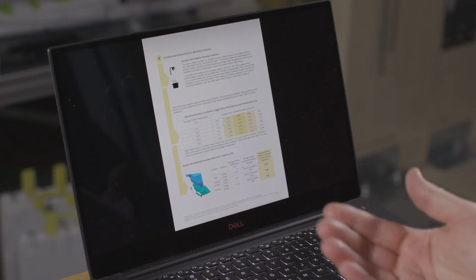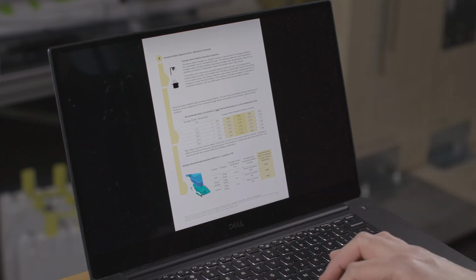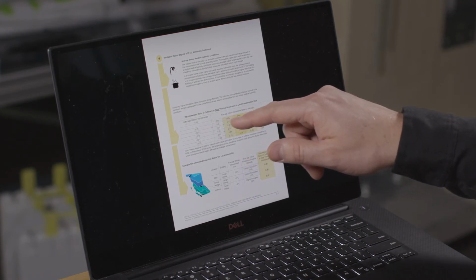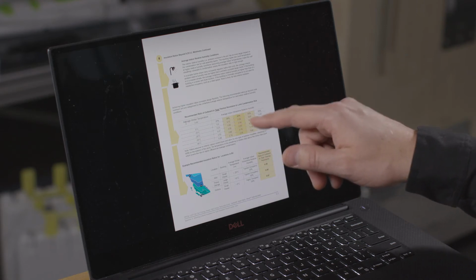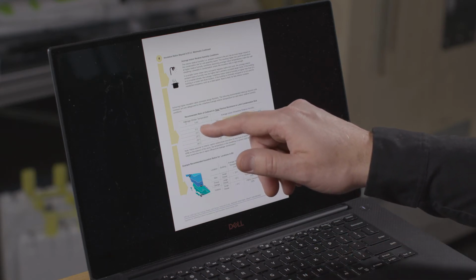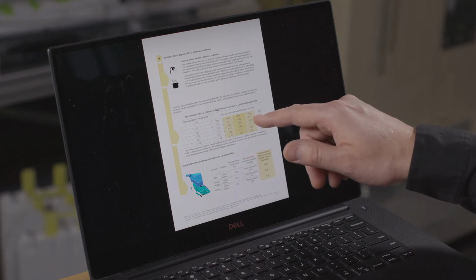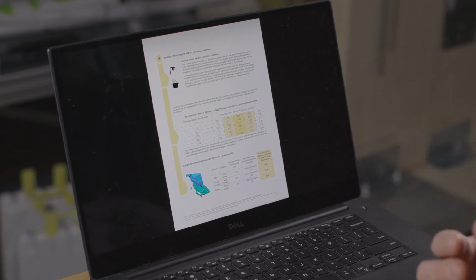When you follow through the building science discussion there, it then gets into some guidance. Okay, what ratio should I have, or what ratio would be safe for this wall assembly? If we look here, we have this table of ratio of outboard to total thermal resistance. Depending on where you are in Canada, you look at your average wintertime low temperature. Say 0 degrees, and then you have an indoor wintertime humidity. There's a bit of discussion there, but generally we're in the 30 to 50% realm, depending on what you're designing for. Let's just say you're designing for 0 degrees, so coastal BC, 0 degree average at 50% humidity. It says I should have around 47%, or a 0.47 ratio, outside to total.